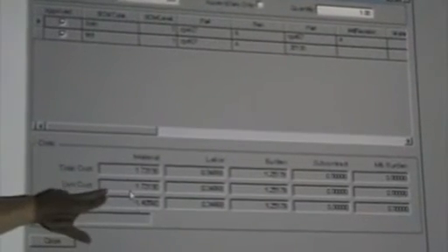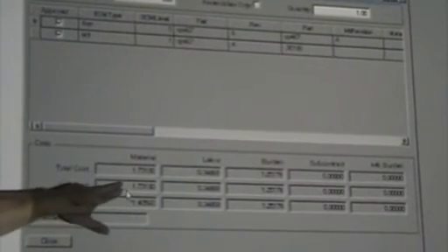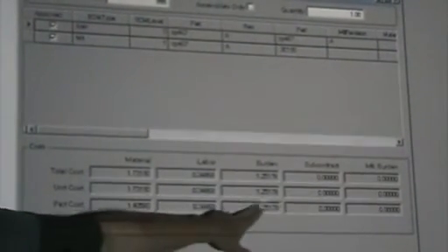That would be true, but actually your current, now we've got to leave this open and go back to your part maintenance, right click and open. Yeah, method tracker. And then just view the cost. The reason the last wasn't updated is because he hadn't done a roll-up. That's correct. They haven't done a roll-up since we changed something in material, because this is the same and this is the same.